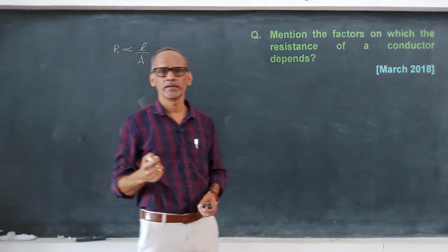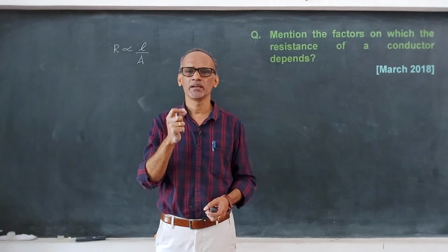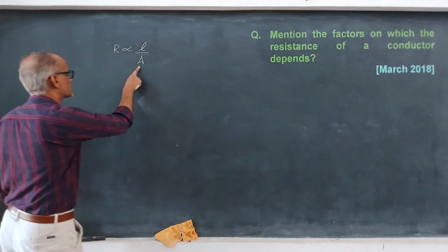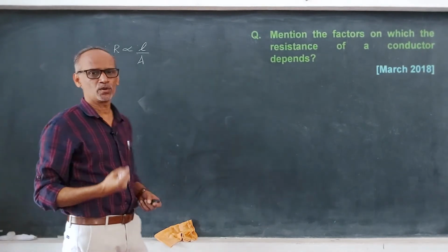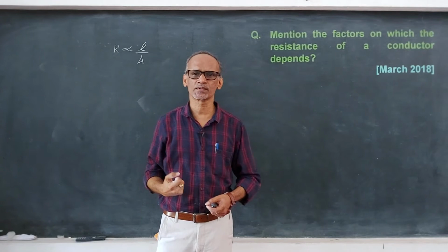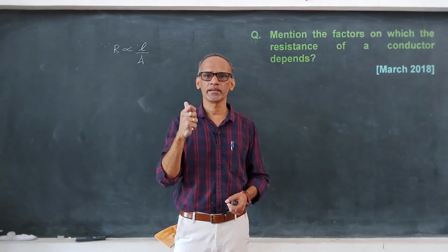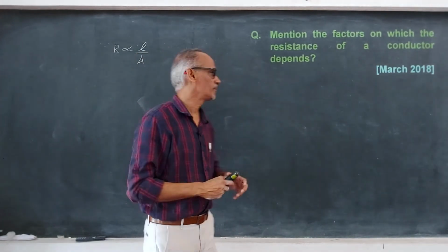That is why in an electric fuse wire, we normally use a very thin wire. The reason being, the lesser the thickness, the more the resistance, and when high current flows through it, the fuse burns very quickly, so that it acts as a safeguard for the rest of the home appliances.